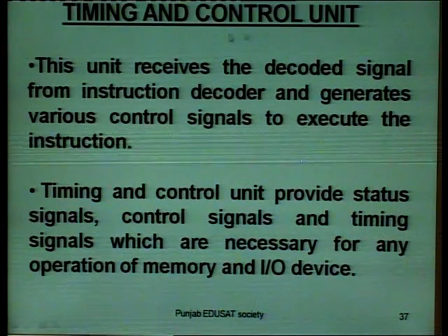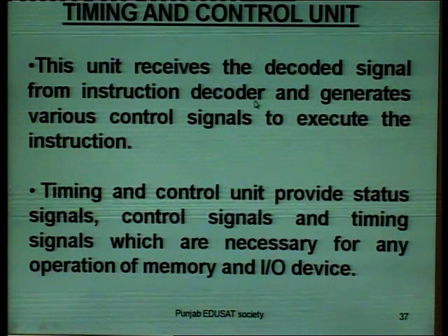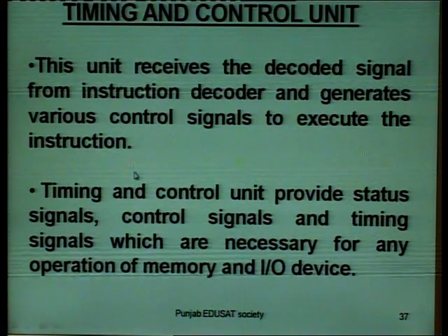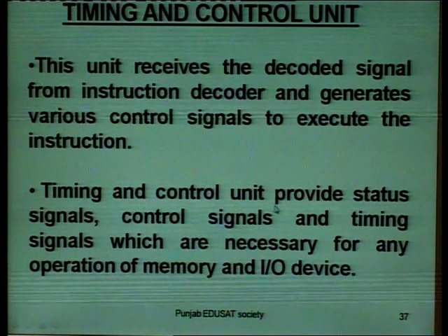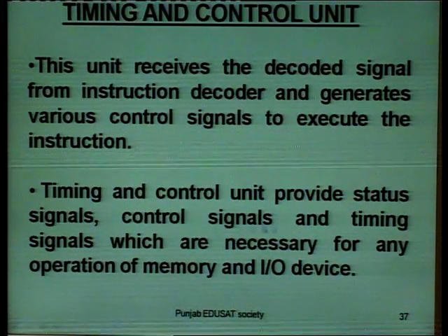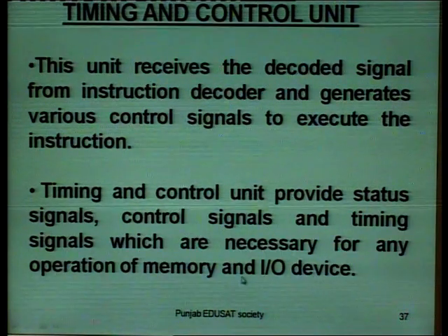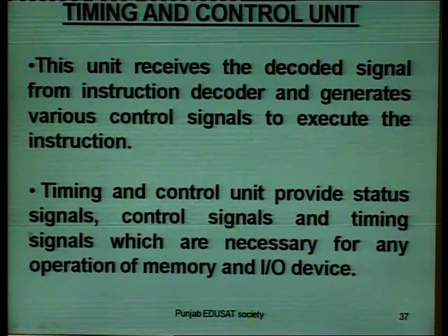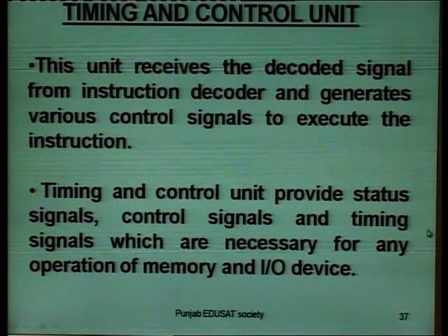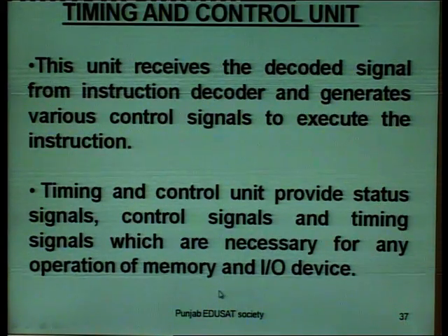Timing and control unit. This unit receives the decoded signal from instruction decoder and generates various control signals to execute the instruction. Timing and control unit provide status signals, control signals and timing signals which are necessary for any operation of memory and input output device.